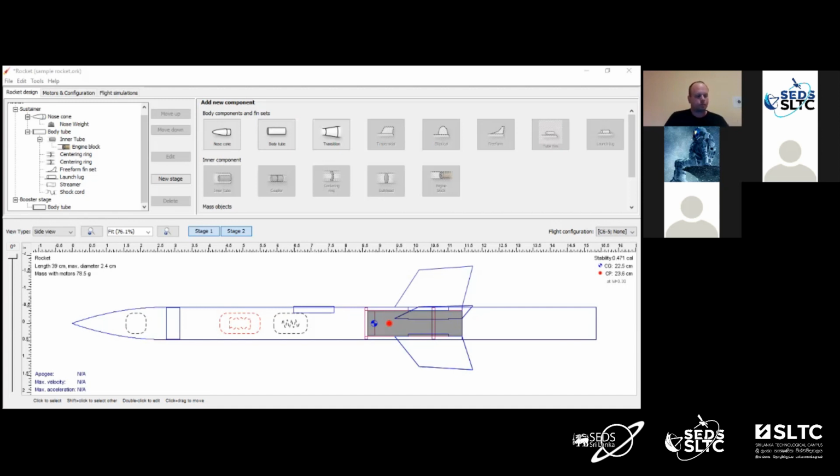So in bigger rockets, we'll have what are called shear pins. They go in the sides. It's just like little plastic pins that go through to hold this securely in place. But when the upper motor fires, it's going to need some help to actually break those shear pins, cuts the pins in half. And sometimes there will be a little explosive charge in here that pops it off, okay? But in this case, it's just, as this upper motor ignites, the thrust coming out is just going to push this right off, okay?